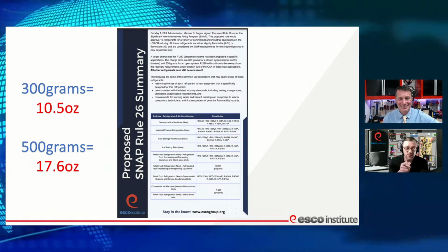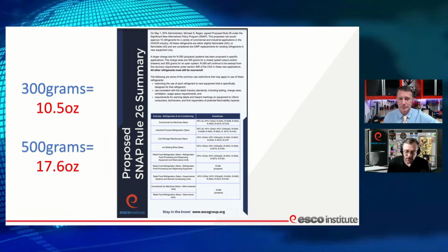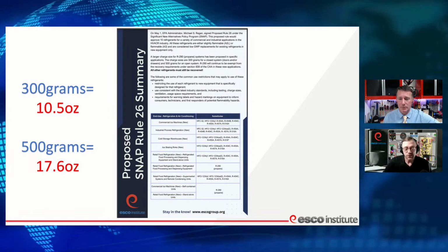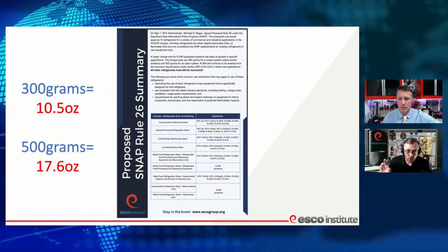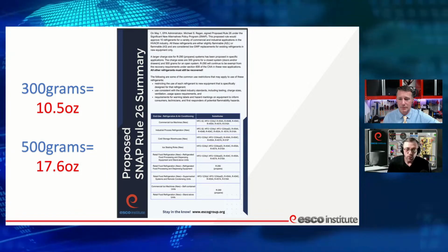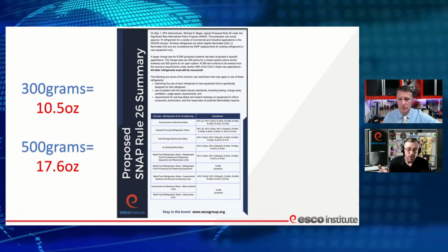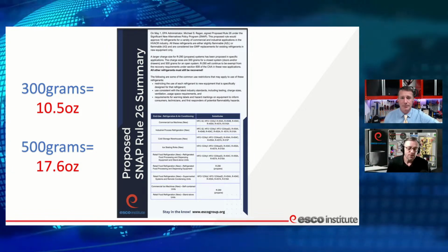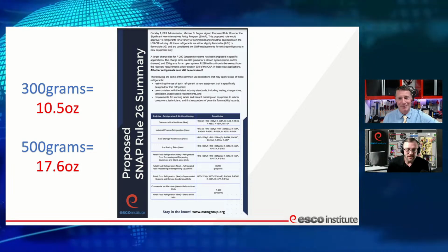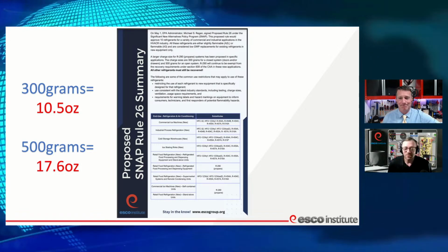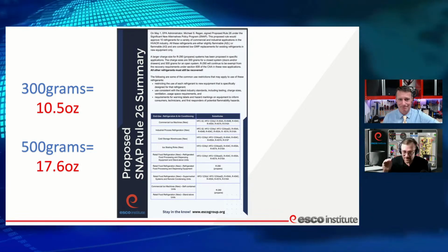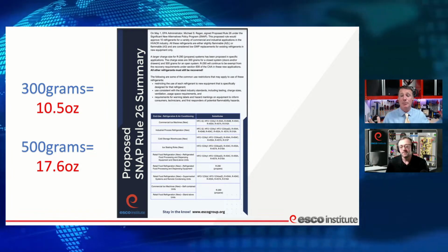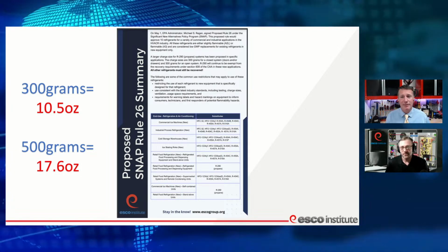I will point out, at these charge limits, we're used to the 150 grams or 114 residentially. These are commercial charge limits, but we will also see on the data plate, as part of this ruling, a required minimum room area that the unit installation could then be deployed into. Correct. Exactly. You can't take this unit, stuff it in a closet, and hope for the best. It'll say right on the data plate, listen, the minimum room area is XYZ, based on the charge of this system.